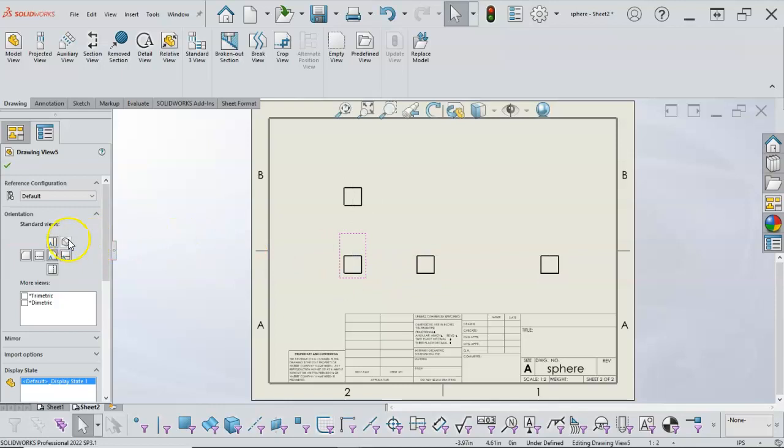All right, so now our isometric is up here instead of over here, and the views. The quick way I always kind of relate it, there's certainly a lot more explanation, is to the front views: if you are holding the part in your hand and you rotate it to the left, you see this. If you rotate it to the right, you see this. You rotate it up, you see this. If the part's sitting on the table and you're walking around it, then the right is looking at it this way, the left is looking at it this way, so effectively opposite.